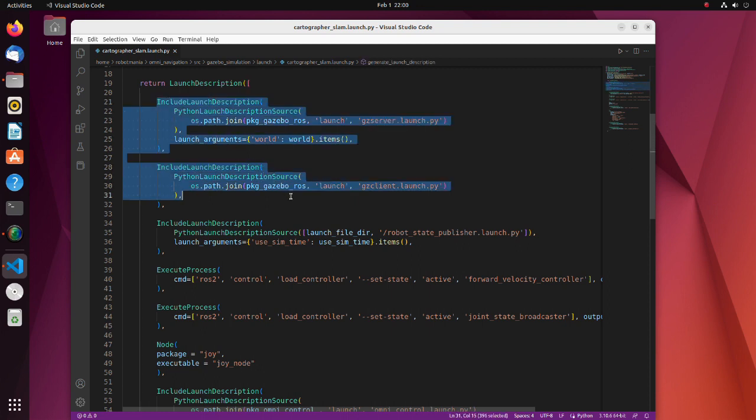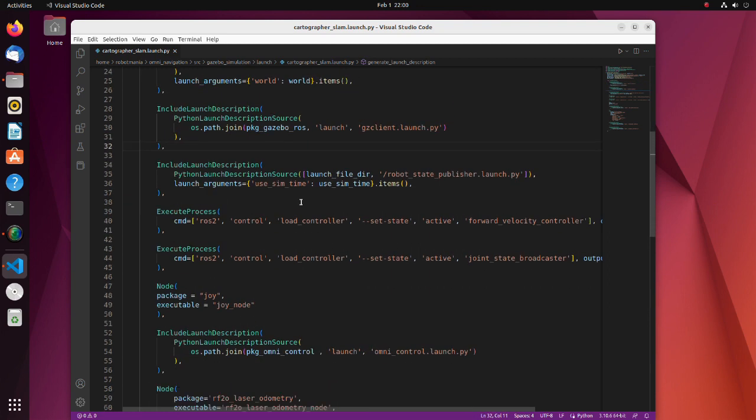In this chunk we are launching Gazebo. Here, Robot State Publisher is launched. This package allows you to publish state of the robot to TF2. Once state gets published, it is available to all components in the system that also use TF2.